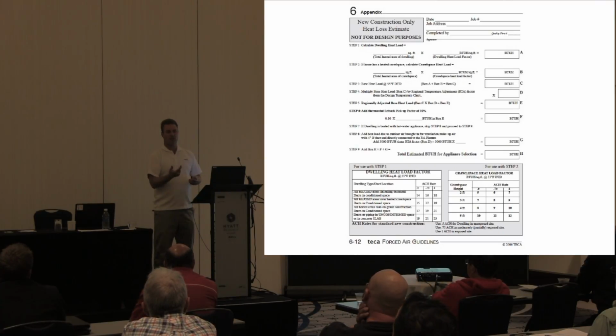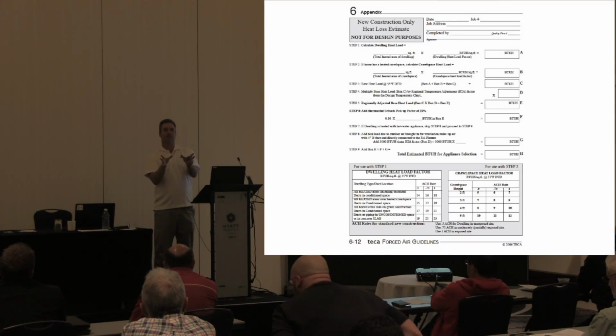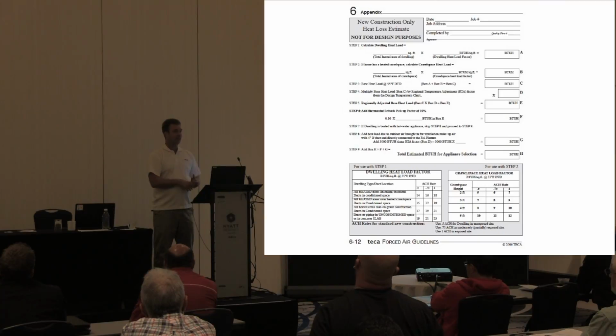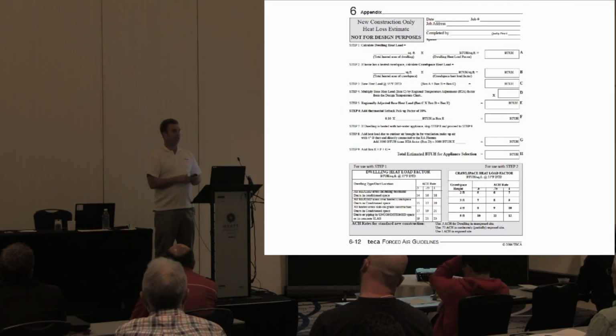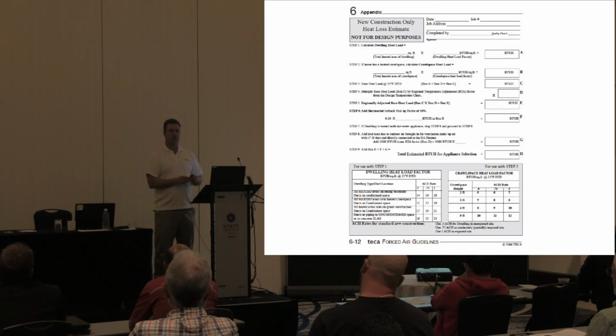But a lot of times, to put the zone system in and try to serve that one master bedroom that they want at a different temperature, like you discussed, it's not far off cost-wise from just putting another smaller system in. Because a zone system's not cheap to start with, and then once you get into controls and how many dampers you need, it's more. And comfort-wise, it'll be way more comfortable to have multiple systems as opposed to just having it turn on and off when it needs to.